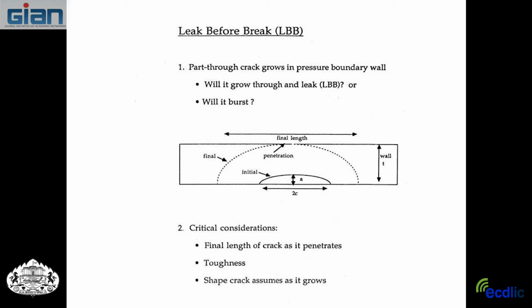It's hard to see, but say you cut the pipe and you look at the cut part, and here's a flaw on the inside. So that's a flaw. Now, for that flaw, you assume that it should grow in a certain way, and then when it grows far enough, it'll get to the outside of the wall. So this would be the inside, where you might have something maybe not bad, maybe water, air pressure, something like that.